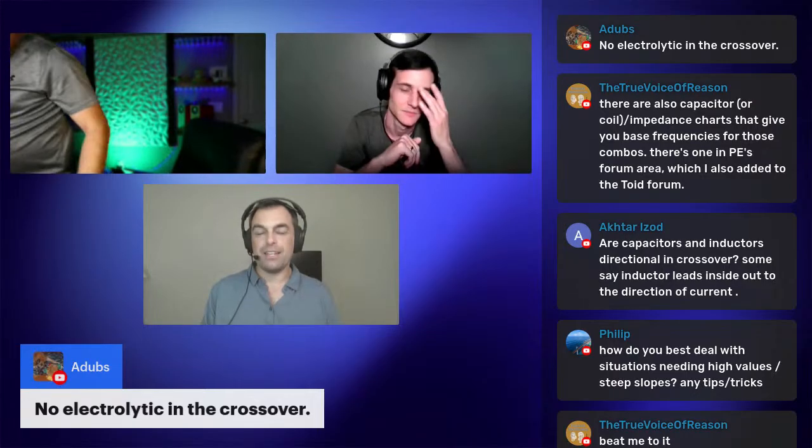Lots. The only thing I understand to be bad about them is they can drift over time, which is a problem. So when you design a crossover, now this is for advanced crossover designers, you should do a sensitivity analysis. Anybody in the engineering world knows to do this.